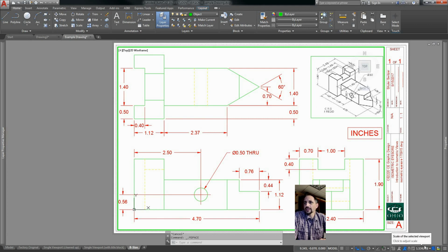As you can tell, there's a scale option for your viewport. There is a lock option so that when I'm finished modifying my drawing, I can select this and it'll lock the viewport to prevent any unintended changes. Always lock your viewport before you submit your homework. Otherwise, you can accidentally change your scale. You can also toggle to show the annotation scales, and you can also force annotated objects that are at different scales to show up. All very useful commands.